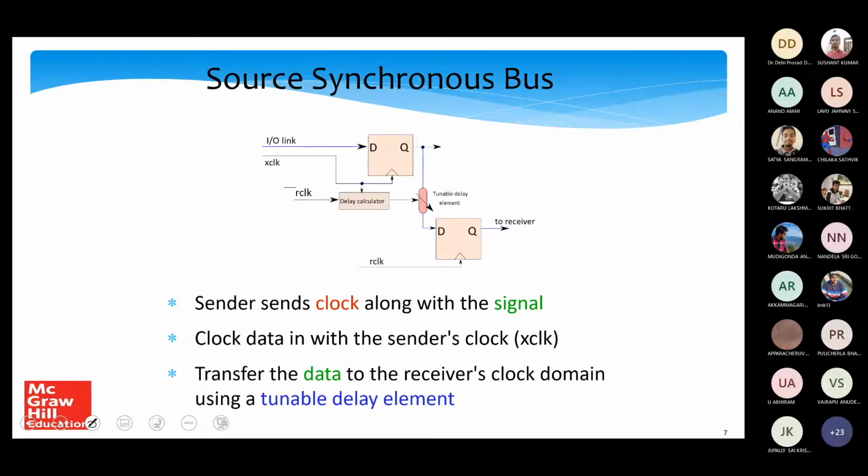After all, on a motherboard, any source and destination chip are separated from each other by some centimeters, maybe 6 inches, about 15, 20 centimeters maximum. So send the clock. It means that a lot of clock signals actually snake around the board. But it's a very simple way of making sure everybody hears the same boom.